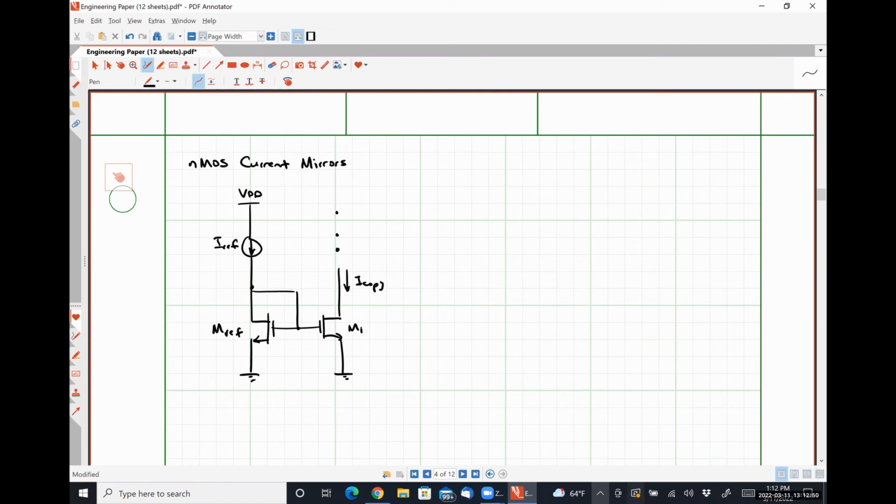So let's talk about scaling real quick here. When we scaled BJTs, we did so by connecting BJTs together in parallel. We can effectively do the exact same thing with MOSFETs, or if we are dealing with a microelectronic circuit that's integrated, we can do that exact same scaling by just changing the aspect ratios of the transistors, right?